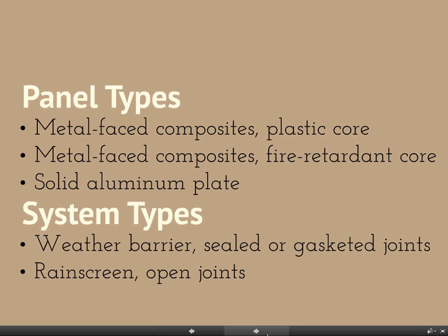And the client, this seismic joint was a pain in the neck anyway for lots of other reasons, because it had to move in 3 directions. So it was just one more nail in the poor thing's coffin when it didn't match visually. Because as soon as the sun hit it at a slightly different angle, or because it was spray coated instead of coil coated, the little metallic particles just never reflected the same as the ones next door.